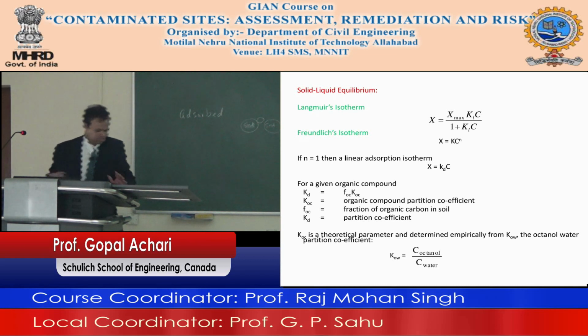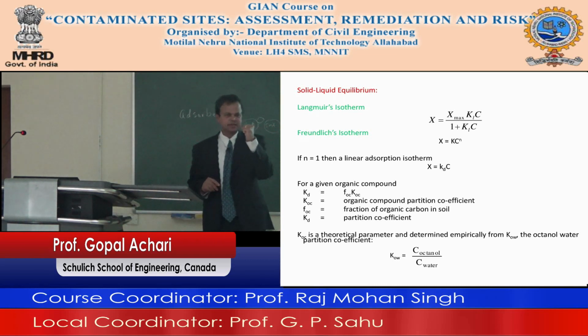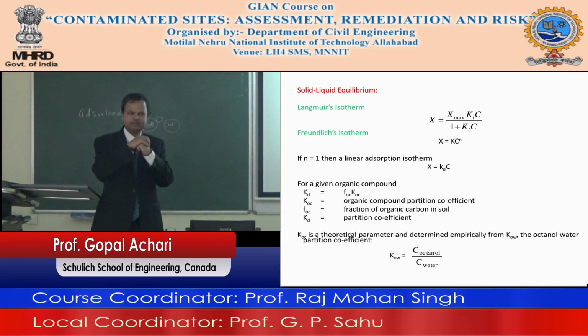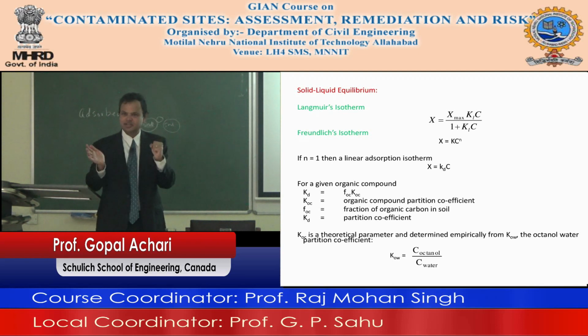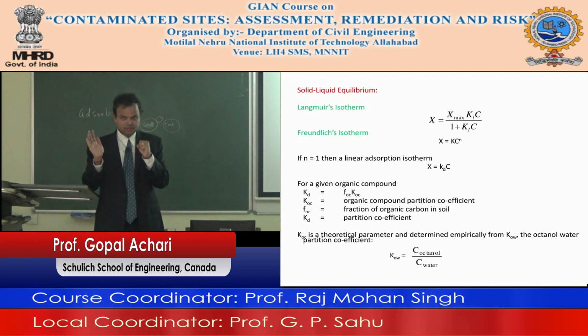Okay, so good. So here is the thing. Let's say this is a sand grain, my fist here, okay? A magnified sand grain. I can have adsorption. Now, I can assume that there are specific sites in which adsorption happens. And if those sites are occupied, then it's gone. It doesn't matter what is present here. Those sites are exhausted, right? That is known as the Langmuir's philosophy, okay? And the isotherm that comes out of it is known as Langmuir's isotherm.